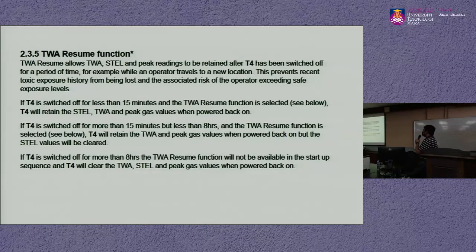T4 will retain the TWA and peak gas values when powered back on. It will still retain STL, but the STL values will be cleared because it's more than 15 minutes. Okay, if T4 is switched off for more than 8 hours, the TWA resume function will not be available in the startup sequence, and T4 will clear TWA, STL, and peak gas values when powered back on.